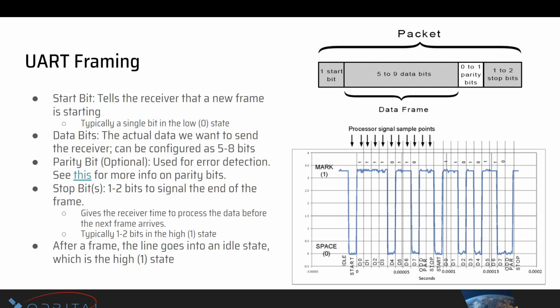Yeah, so like we mentioned, your controller would be a separate little thing, so you're able to run your thread of execution, run your code, while you have another module, because it's just hardware. So your hardware is receiving and storing the data over UART, and you're executing your code at the same time. And then when you actually want to read that value that you received, that's when you have to have some kind of code to read from that hardware and read that value into memory.